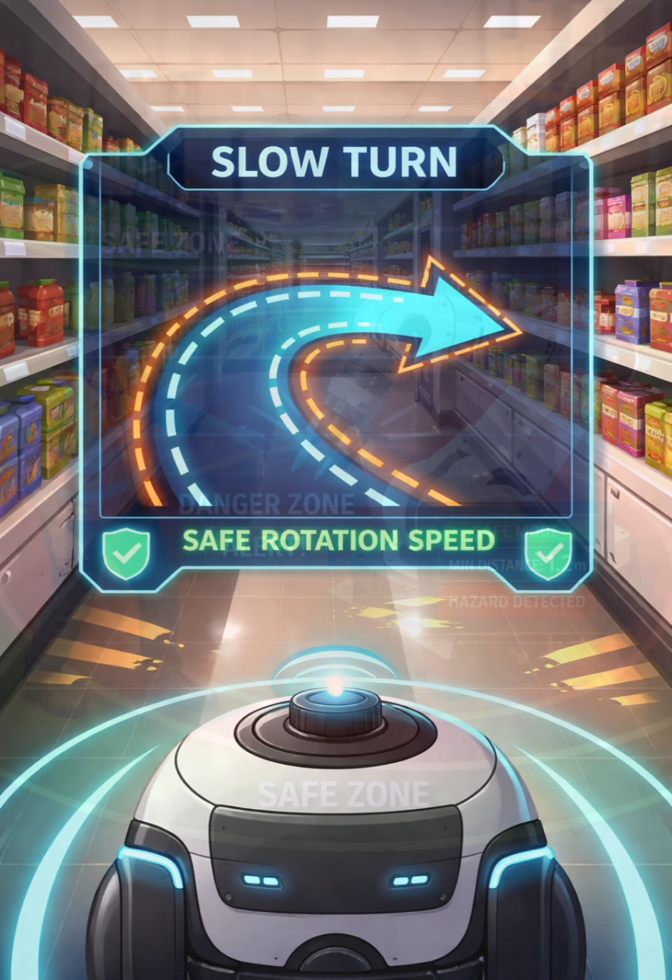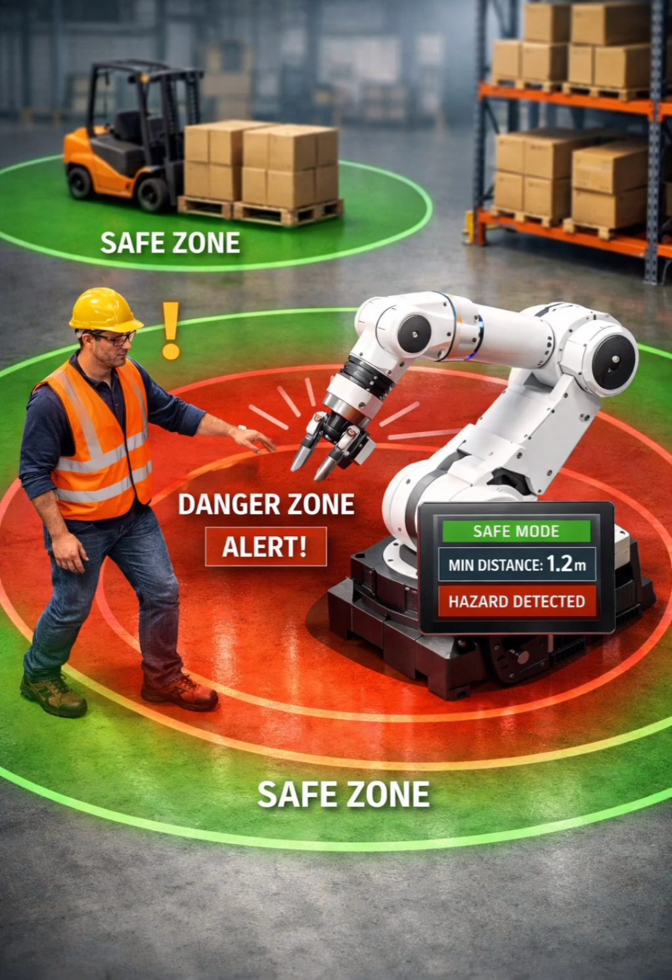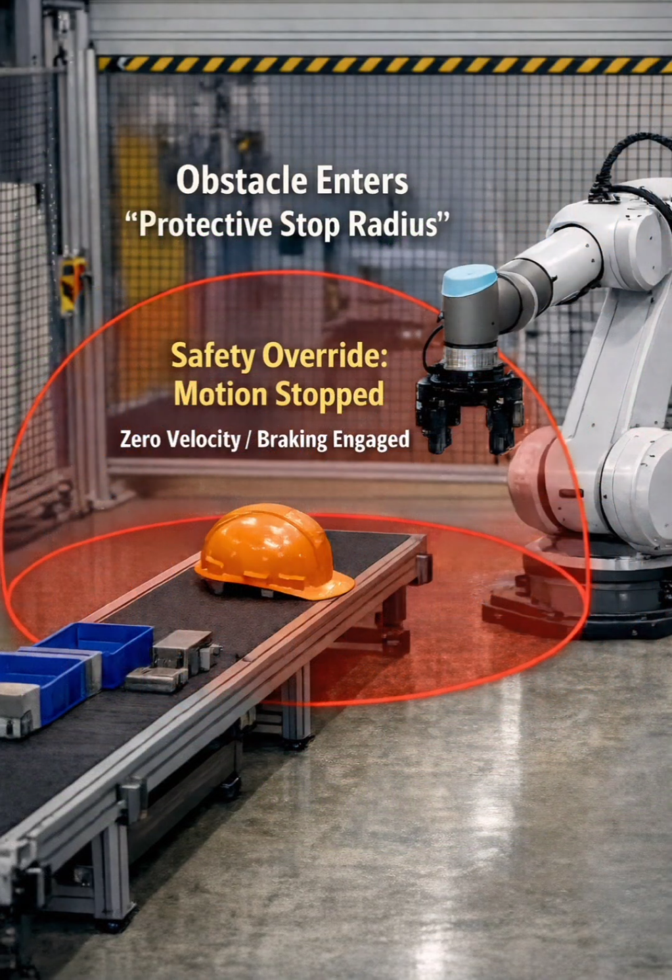Second, it monitors the environment for immediate danger. It uses perception-derived signals, like minimum distance to obstacles or humans, to maintain protective zones. Example: if an obstacle enters a protective stop radius, safety overrides motion and commands zero velocity or braking, regardless of what planning wants.